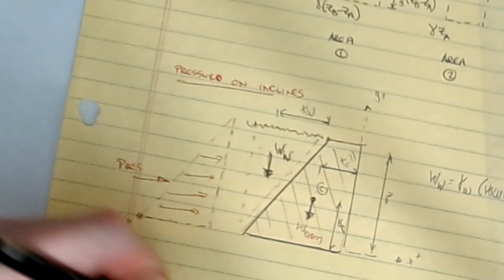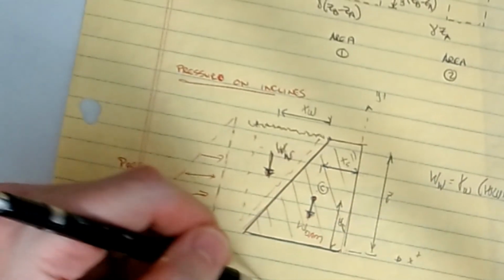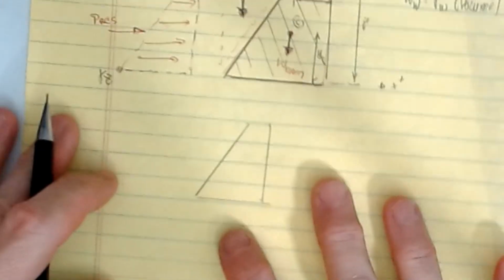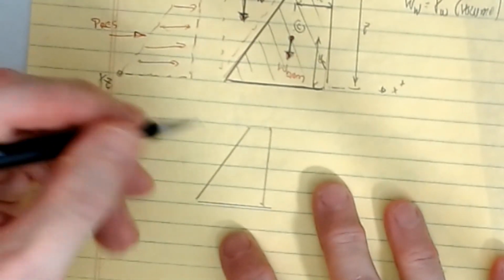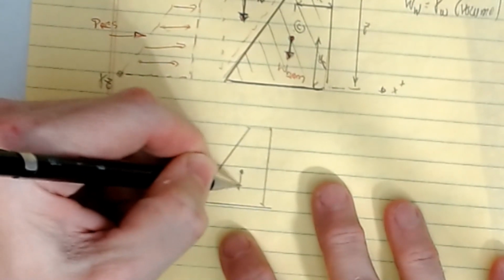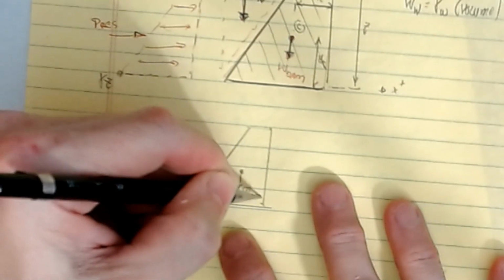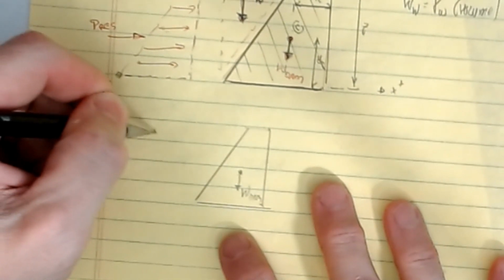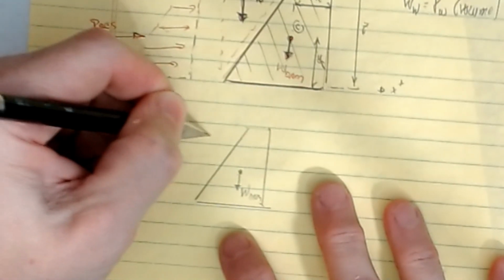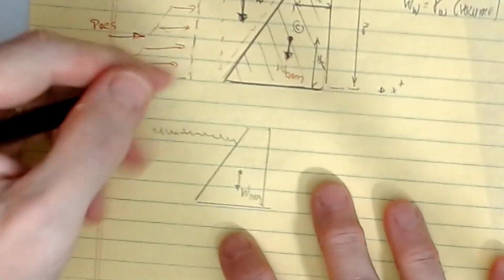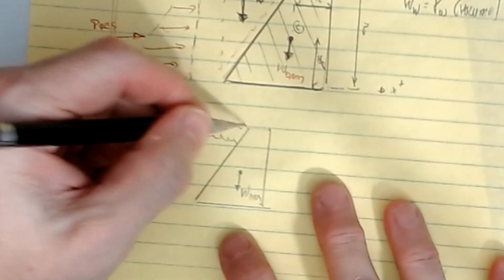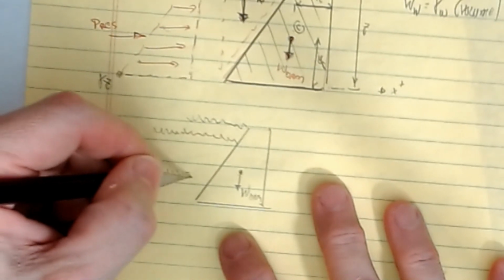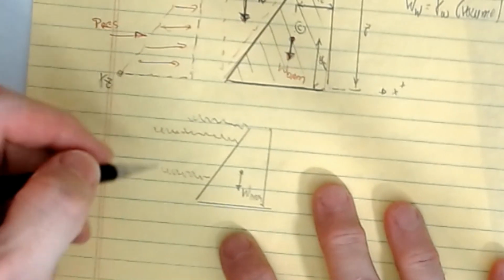Now, one thing you have to watch out for, which happens in a lot of our Beer and Johnston sample problems and even to some degree in design, is that as you're designing your dam, especially for a water control problem, this depth may vary. At one point in the season it may be all the way up at the top, and then during the dry season, or when farmers start pulling water out to water their crops, it may move down.